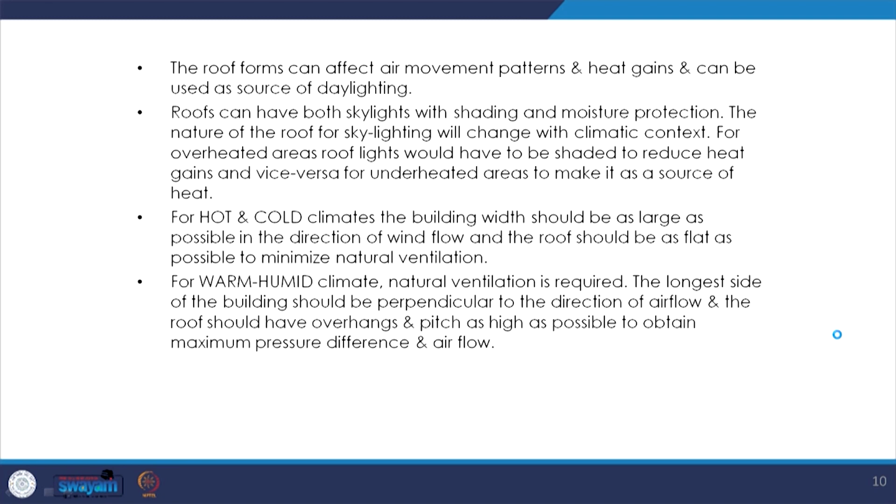Besides the air movement and solar radiation and controlling the air temperature, these elements also help in controlling the daylight. Suppose we plant deciduous trees towards south. So, in summers these deciduous trees would shade the building and control the direct radiation and also the daylighting, while in winters when they shed their leaves, they allow a lot of sunlight and daylight to penetrate inside the building. So, together these elements control a lot of environmental parameters.